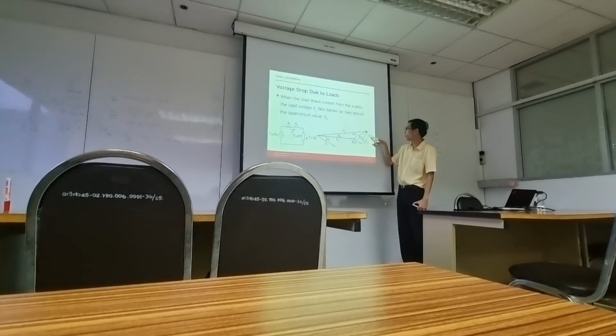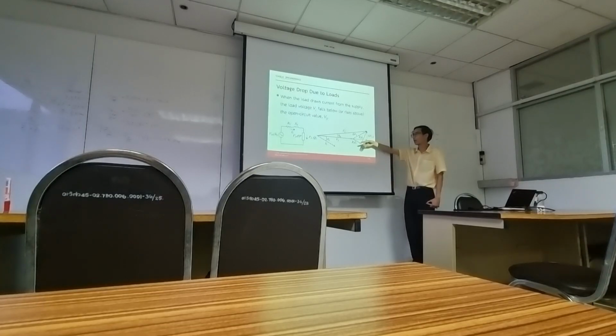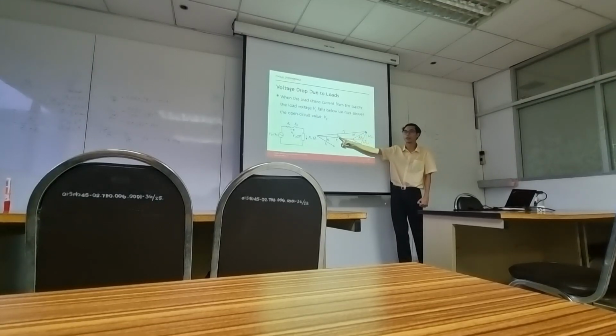Okay, this component delta VLX has a lot of impact on the angle. It does not have a lot of impact on the length of VS and VL. This delta VLR has a lot of impact on the length of VS and VL. Right? You can see that because delta VLR is in this direction, it has a lot of impact on the voltage magnitude drop. The delta VLX has a lot of impact on the angle.